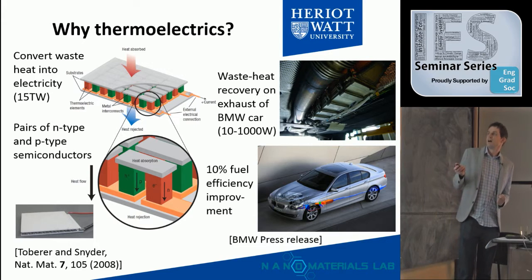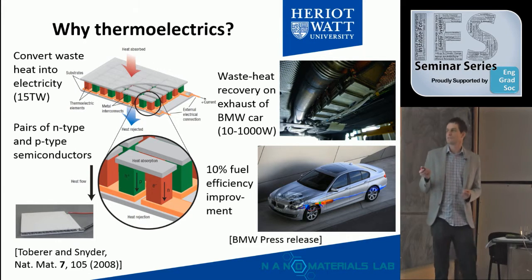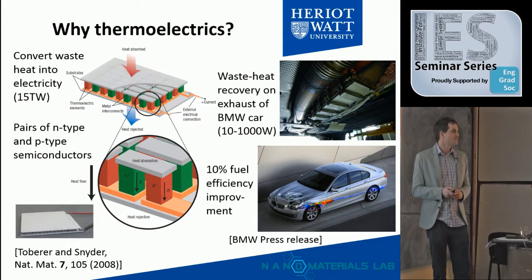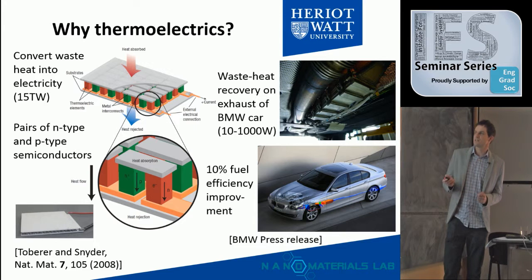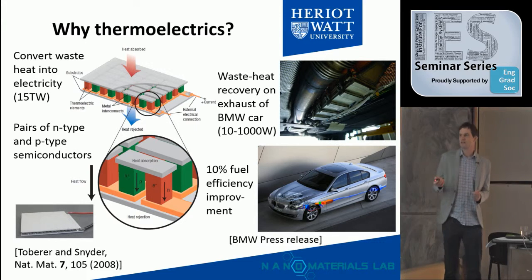So the devices are quite straightforward, as you hopefully can see. We tend to have a couple of ceramics, top and bottom, some thermoelectric pellets, P and N type semiconductors as the active part in the middle, and then those are hooked up with metal interconnects to keep everything in electrical series. And you can see here a close up there.